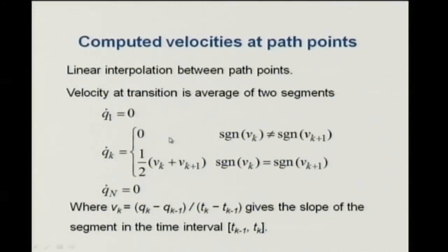In that case don't take the average of the 2, because this works better. Otherwise there is a problem with drift and a couple of other things. If the input you're getting is reversing signs, just keep the velocity 0. Don't take the average of two velocities, because that causes control instability.